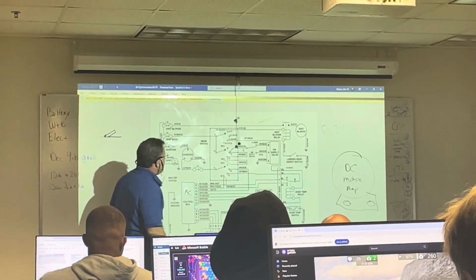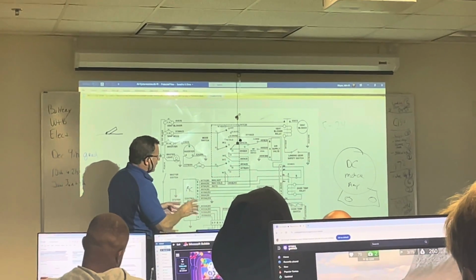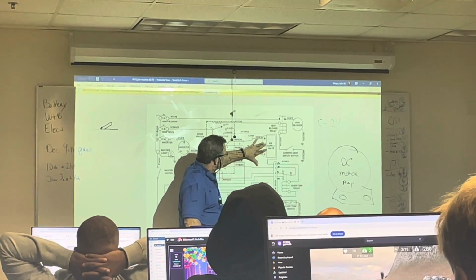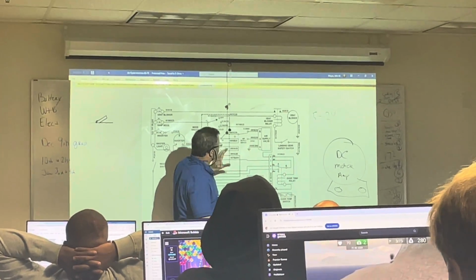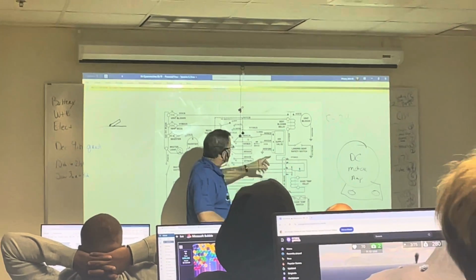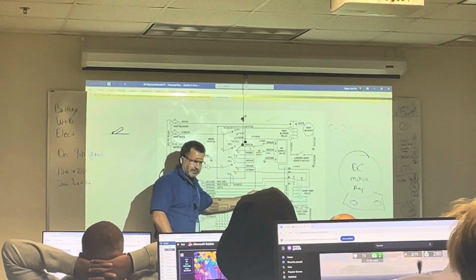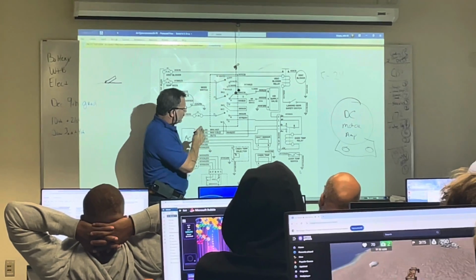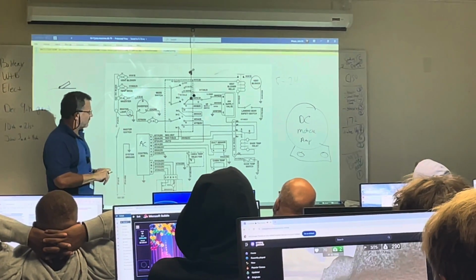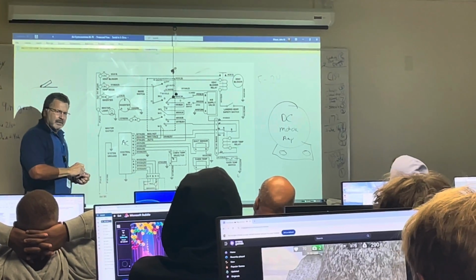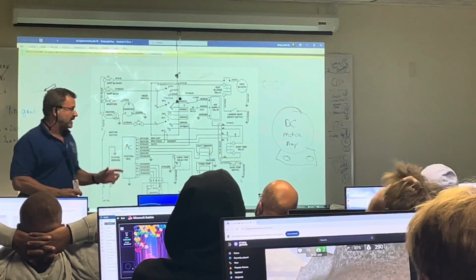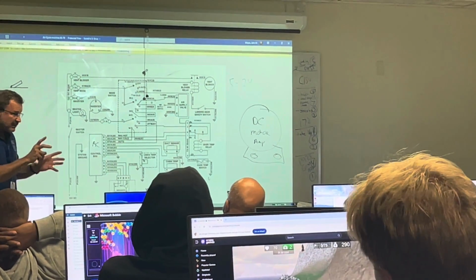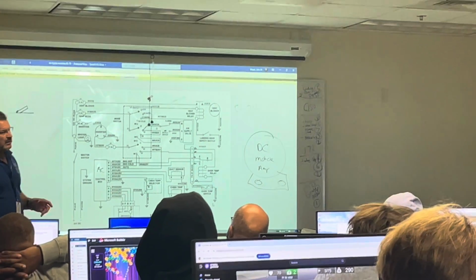When we look at our test strip or terminal strip, number 1 bus, we have our air supply valve. None of the air conditioning works without an air supply valve. We have that as a source of air, right? Right. Okay, and then down here we have duct sensors. Now, you're going to see duct sensors and cabin sensors. You're looking at that symbol. What does it tell you? What kind of symbol is that? The duct sensor is a resistance type of component. Yeah. But as a resistor,